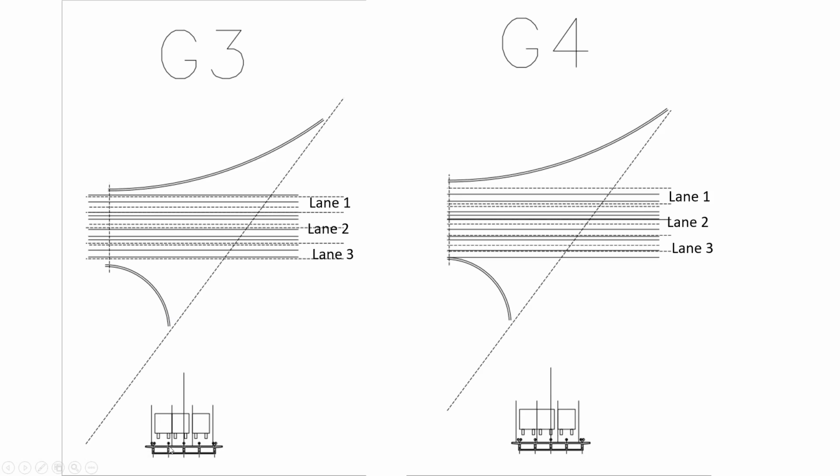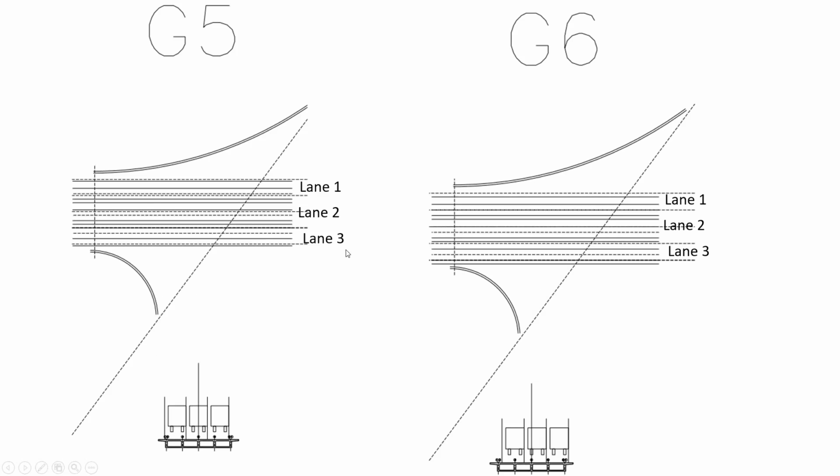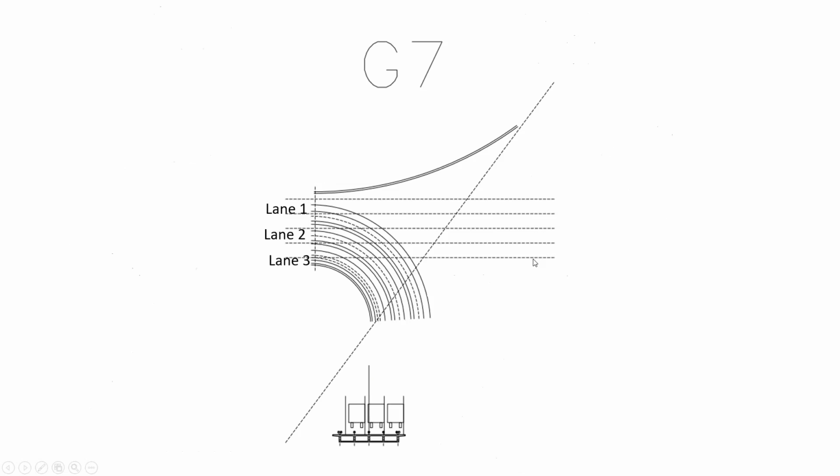So I put the wheel load just on top of girder 3, and I accommodate the other trucks accordingly. I continue that process for every single girder. I need this information in order to put it into MIDAS, because MIDAS needs the eccentricity of the truck at every location. So I'm going to continue with girder 7.